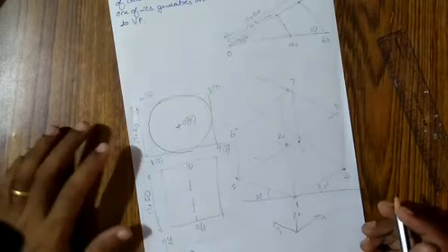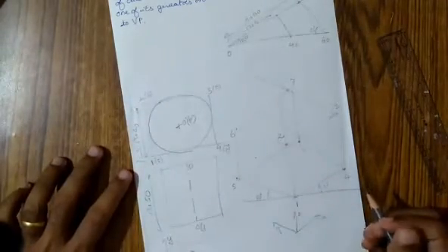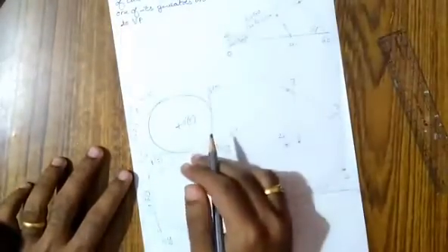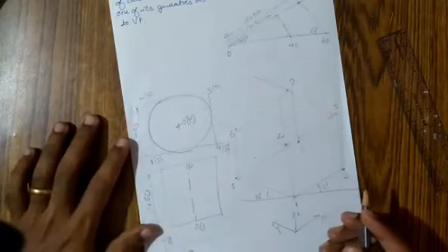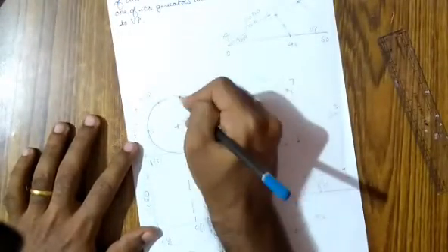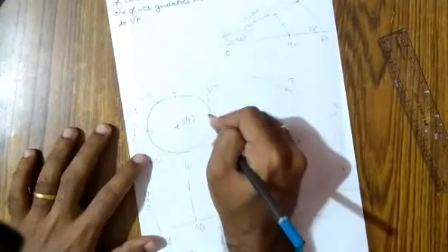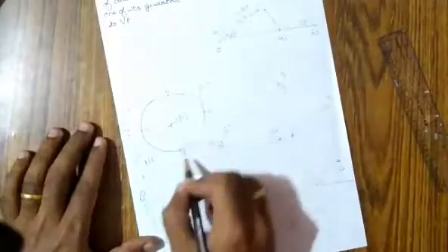Okay. So you have to draw a cylinder inside this box. The front circle is lying on the face 1, 2, 3, 4, and the back circle is lying on the face 5, 6, 7, 8. So let this intersection point be A, B, C and D. So A, B, C and D are the midpoints of 1, 2, 2, 3, 3, 4 and 1, 4.